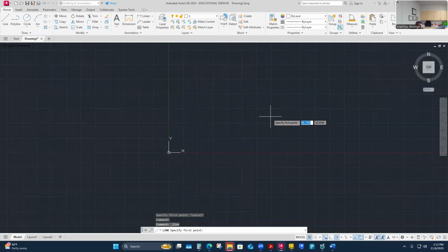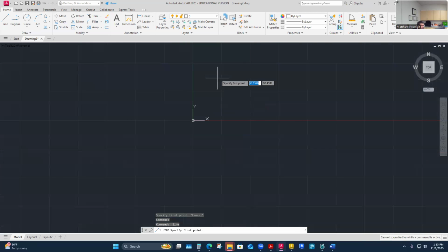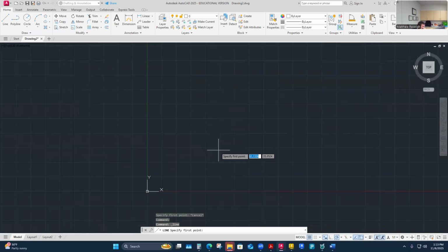In some cases, with some machine drawings, there'll be a strategy in what coordinate you put it at. Sometimes when you're building drawings for machinists and the G code is going to come from your drawing, maybe it matters what coordinate I'm starting with. There might be a 0, 0 point the machinist wants this part designed around. So that's where it matters to me. For us, I don't care where we draw. Generally, when it doesn't matter, I'm going to draw in a positive quadrant though. So I'm going to draw up here somewhere.